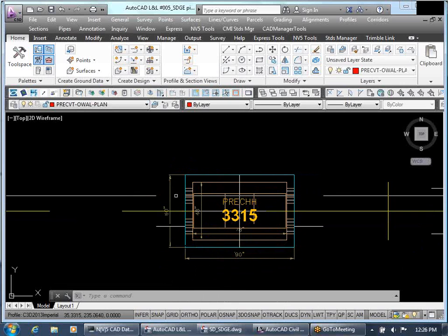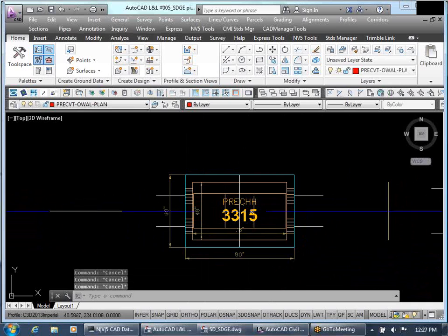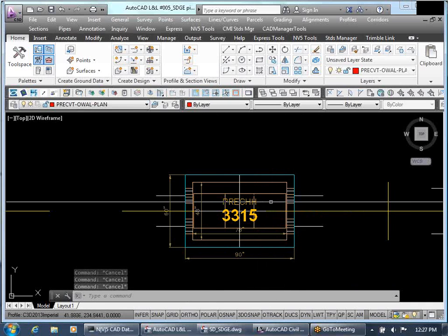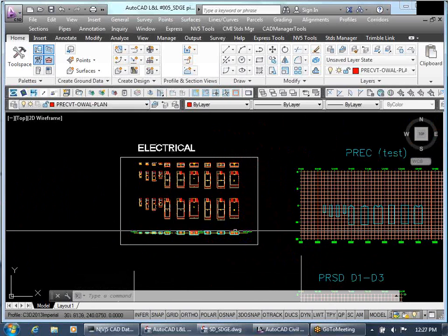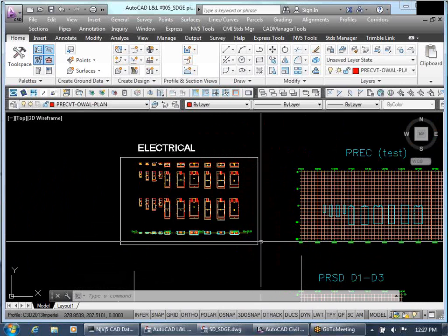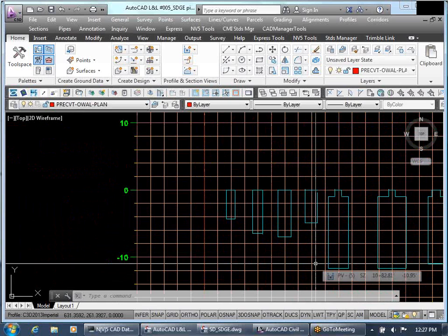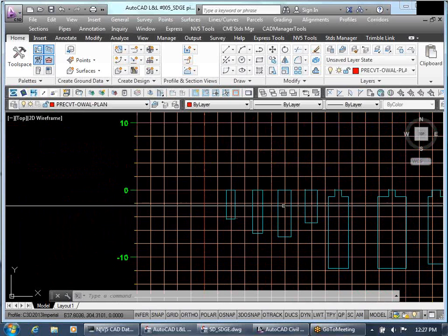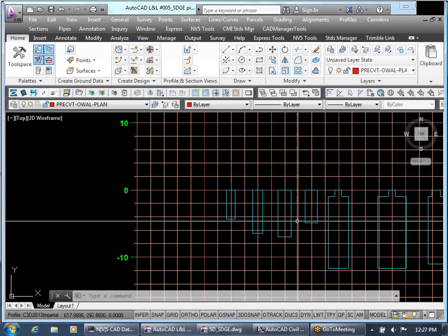Always check something once. Make sure that these knockouts are the correct dimension that you're anticipating. This is 2 feet off, so you can start your curve there. Little things like that can really speed up your process and make sure that you have exactly what you want to have. So there are those guys in plan view. If we just use a pipe network for those, this is the level of detail that we're going to get. Those first 4 handholes are just simple box structures, nothing very special.